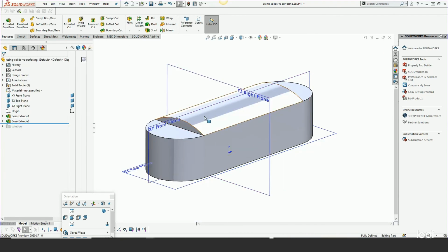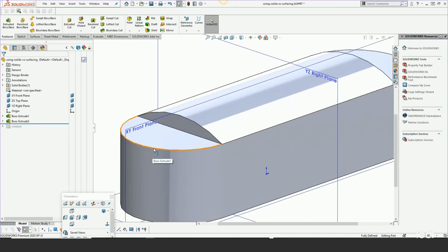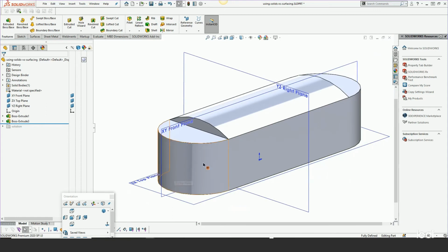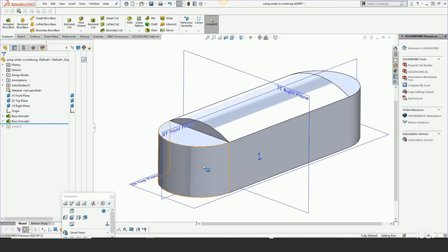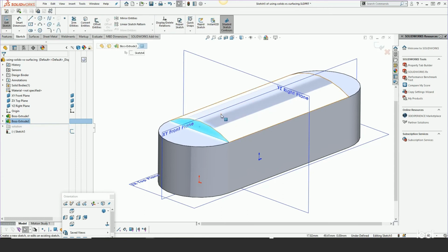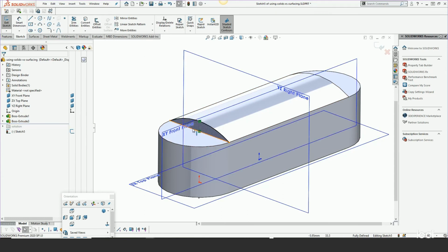Now what do I do about the end caps? Again, I could delete surfaces here and maybe do a fill, because remember, this is really three-sided, because you see just two boundaries here, but these coming to a point and these boundaries sharing the same endpoint is also an issue, and I'll get into that in more detail in a future episode, why you wouldn't want to do that with boundary. You could do it with fill, but the simpler thing to do is to just pick this face and do a convert edge.